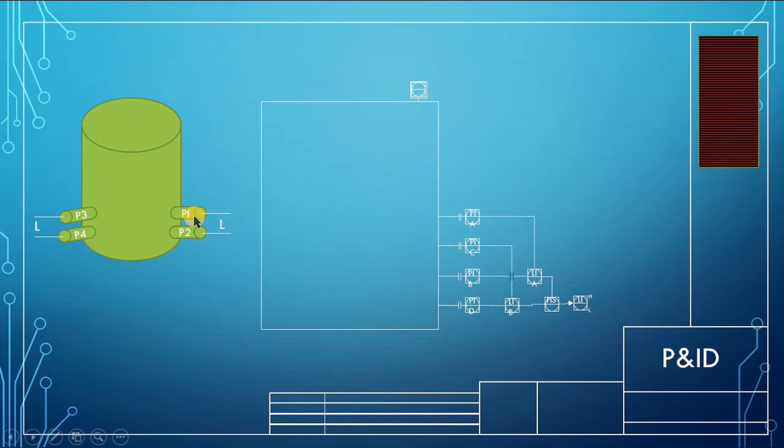Because of the variable density, you can't rely on one pressure. So you need to measure the pressure at two nozzles with a specific known distance between the nozzles. You use the difference between the two pressures to calculate the density. Then you use the bottom one to measure the actual level based on the newly calculated density.